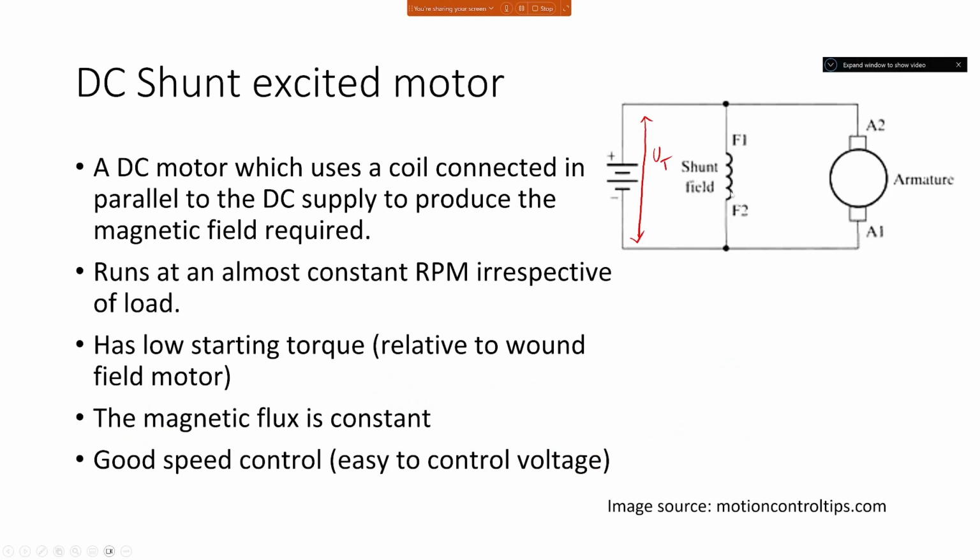And this shunt takes a current. Yes, of course, it's a real device. It takes some current, but it's really small. So I shunt is much smaller than I total, so you can ignore it. That's what we do. We ignore the current consumed in the shunt. And there are two types of motor. In this shunt excited motor, or separately, independently excited motor, as other names for it, this shunt field is in parallel to the armature.